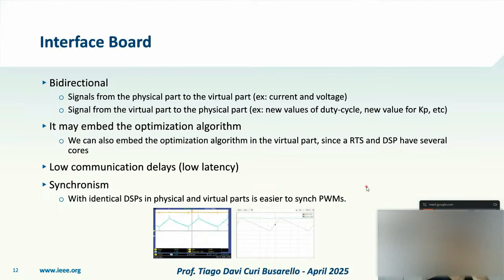And we also have some distance, and maybe a communication delay, so the carriers must be really synchronized. Considering now we have high frequency PWMs, any 1 microsecond, half microsecond of delay may desynchronize these currents and the comparison would collapse.